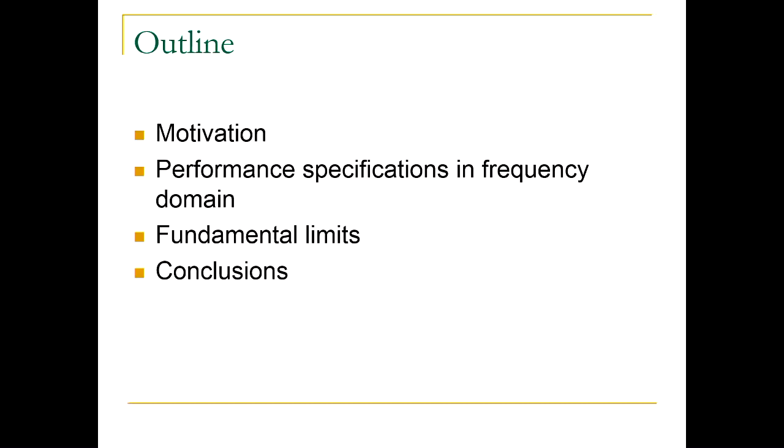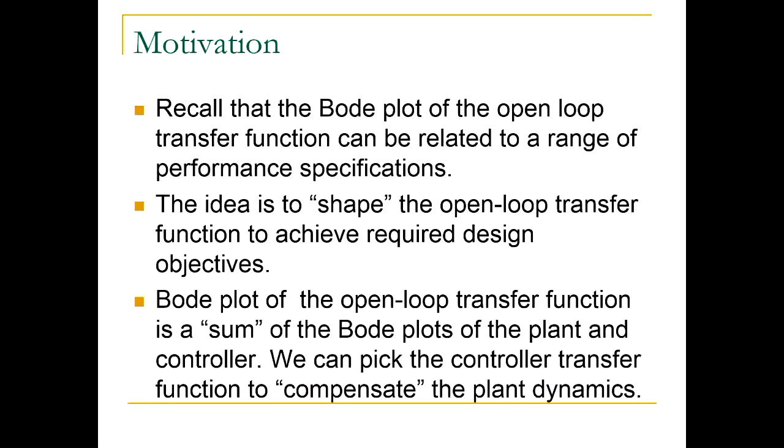This is sometimes referred to as Bode integrals. So there are certain equalities that are called Bode integral equalities, which specify these fundamental limits to what is achievable when shaping your open loop response. So, sorry, the sensitivity transfer function's frequency response. And then I will wrap up with the conclusions. All right.